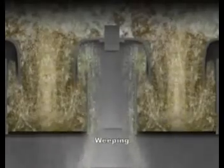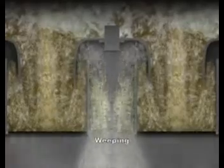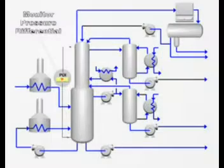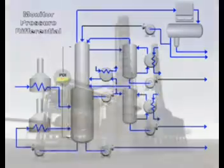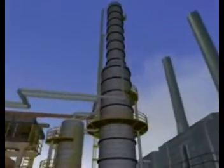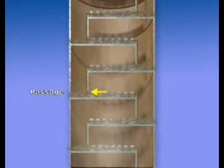Excessive weeping can result in dumping, in which all liquid will move down to the base of the column. The steady state will be compromised, and it may be necessary to restart the process. Weeping can be detected by a sharp pressure drop in the column in combination with reduced efficiency. When liquid levels get too low, an undesired passage to the downcomer area can result.